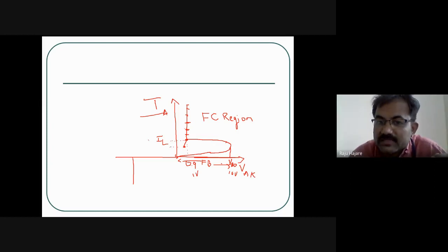In the exam also you have this experiment. That's why I did not say the PPT was completed. I have explained this, but I am repeating. With each stage, this shows what is happening. If you get the point, then it will help in your laboratory exam. Yes, latching current you are noting down as a result part. Breakover voltage you are noting down as a result at which your device is turning on. Holding current magnitude also you have to write in the exam. So that's why I'm telling with this diagram. Yes, so that variation can be observed.